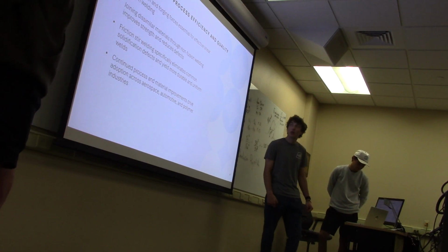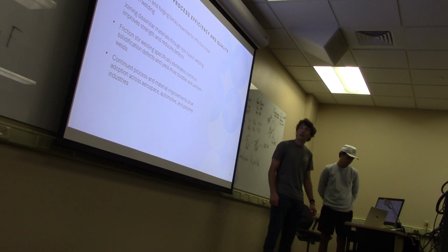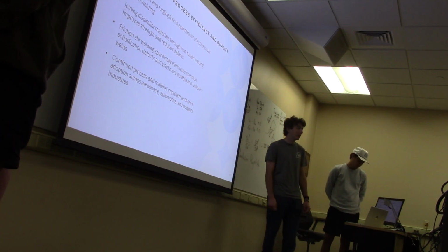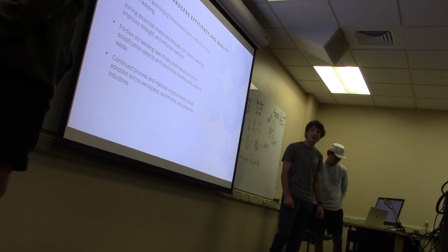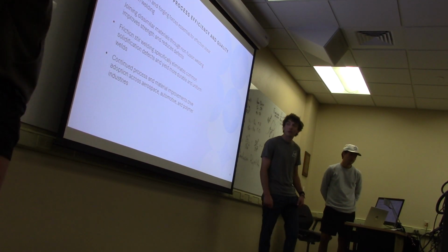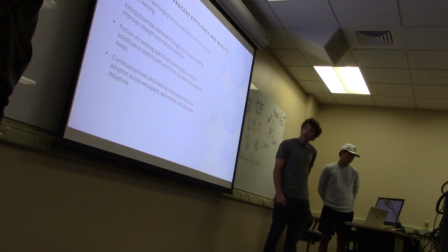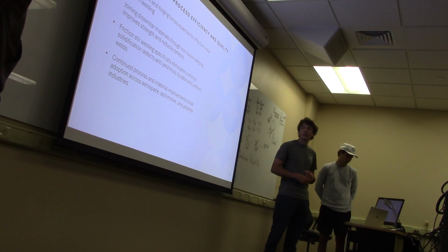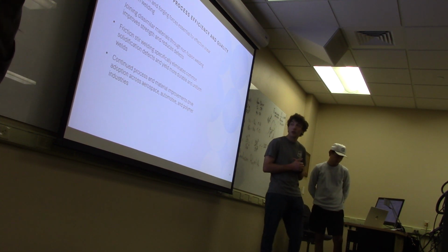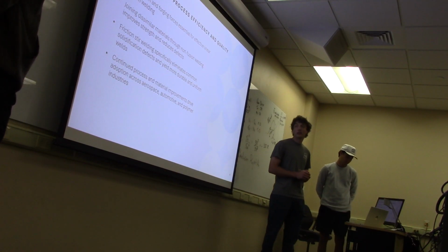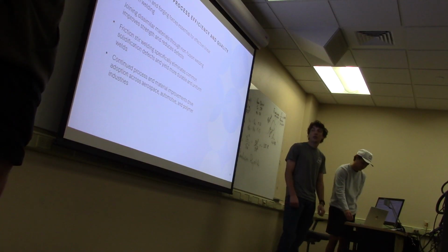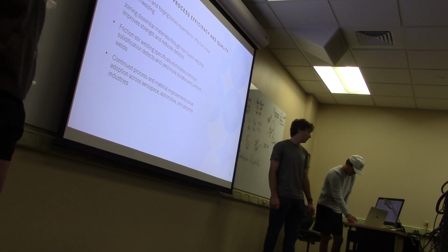So the implications of the process are that high friction and forging forces are essential for effective linear frictional welding. So temperatures can be high around the machine. Then joining dissimilar materials through non-fusion welding improves strength and reduces defects. And then frictional stir welding specifically eliminates common solidification defects and yields more durable and uniform welds. And then continued process and material improvements drive adaptation across aerospace, automotive, and polymer industries.